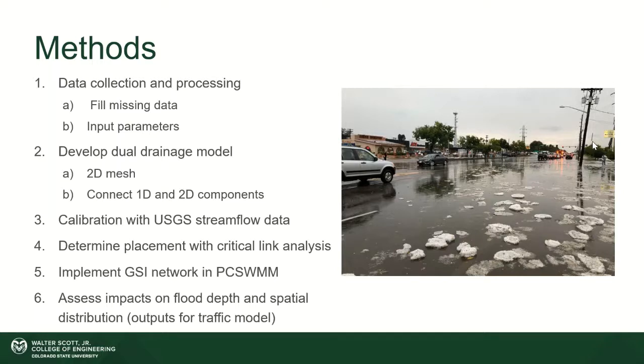And then the development of the dual drainage model, which includes developing the 2D mesh and connecting the 1D and 2D components. And then calibration using USGS streamflow data. And then determining the placement of GSIs in the network using a strategy called critical link analysis.